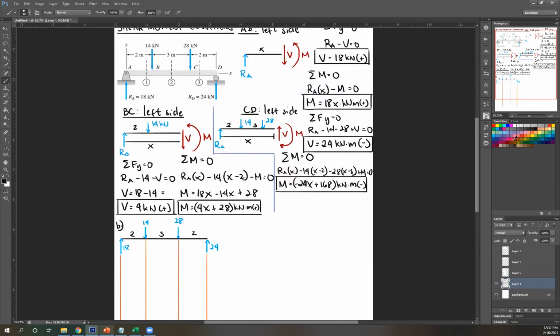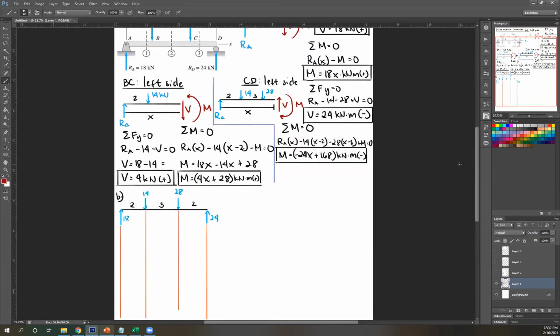Shear. So to start off, you're going to draw your reference line. So let's say this is your reference line, and then this is your shear diagram. So just look at your external forces. You're going to start at the leftmost side where you started your equations with. So I started at left, so start at left side. So this is your 0, 0 point.